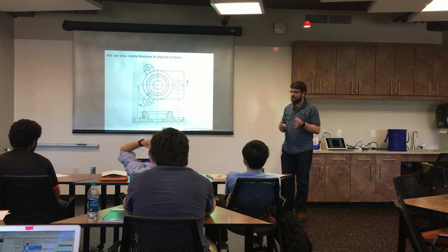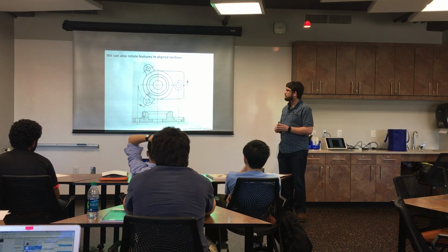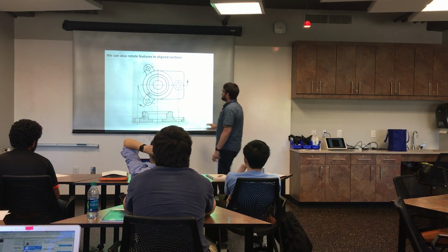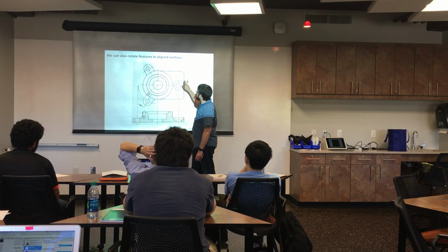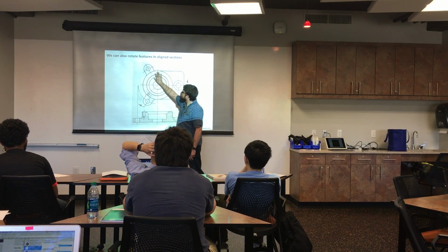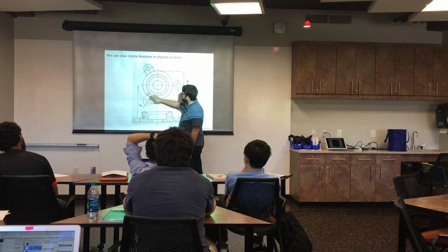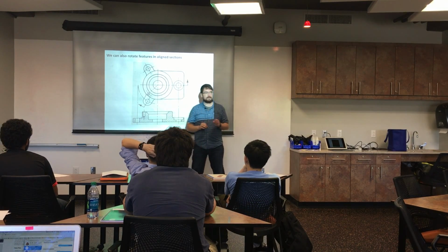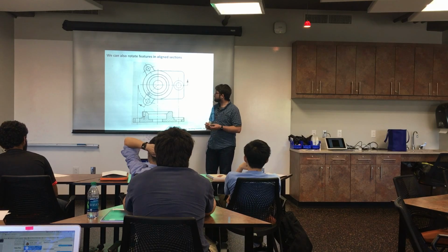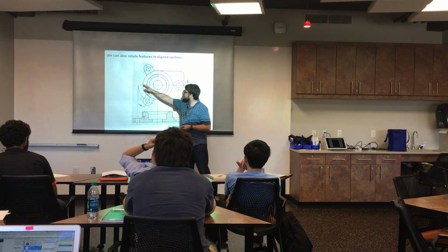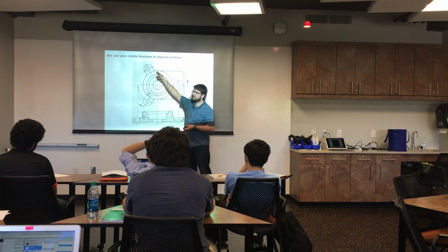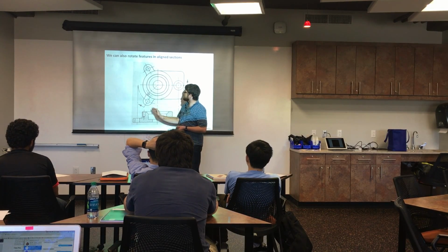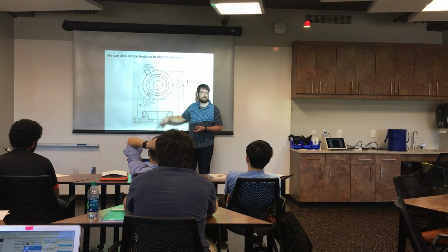The section madness doesn't stop there, because you can also rotate features in aligned sections. So in this part, we've got some kind of squarish thing with a circular boss and a hole in it, and these 2 little mounting ears with holes in them. The most descriptive section view that we could draw, if we just draw a section across here, we get this hole and this hole, but we don't get either of those. We could draw a section across there, but that's kind of pointless. We get a bunch of weird things in here that we don't really care about.